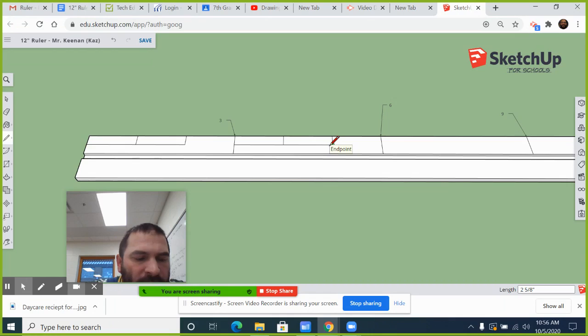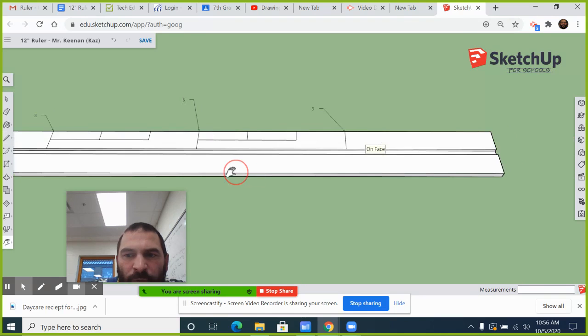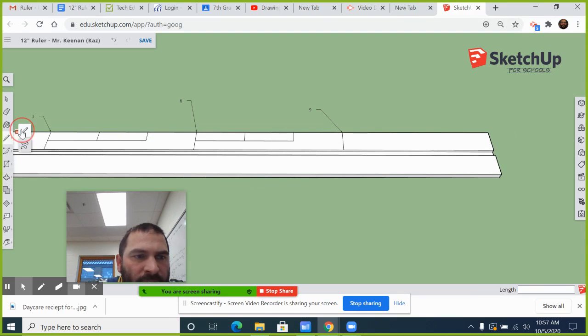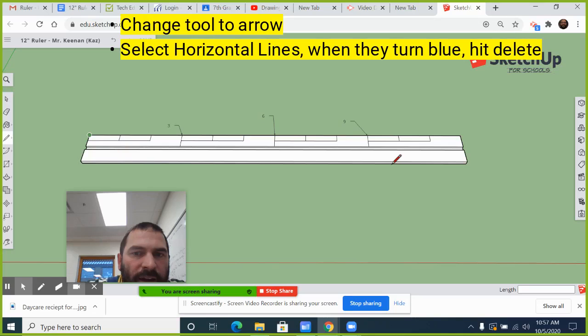From here, 12 inches, enter, and then up, escape, 12 inches, enter, and then up. I'm going to right click, pan, slide this over this way, grab a hold of the pencil again, right here, 12 inches, enter, then go up, then 12 inches, enter, up. So now, it looks a little weird, but I'm going to show you how to get rid of all the rest of the stuff we don't want. Every 12 inches, there is a mark that will indicate 12 inches on this ruler.